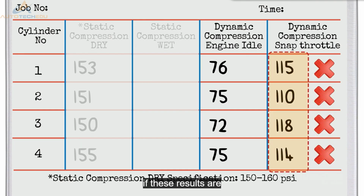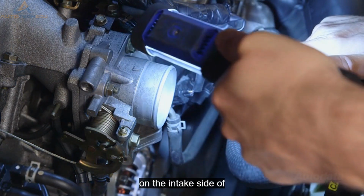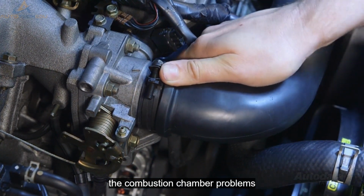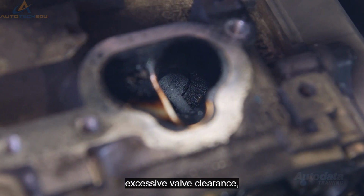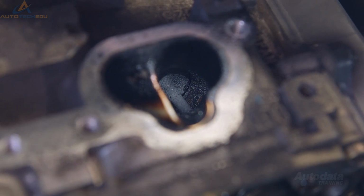If these results are much lower than 80% of the static readings, then check for airflow restrictions on the intake side of the combustion chamber. Problems can include worn intake cam lobes, excessive valve clearance, worn intake guides, or heavy carbon deposits on the intake valve or in the intake manifold.